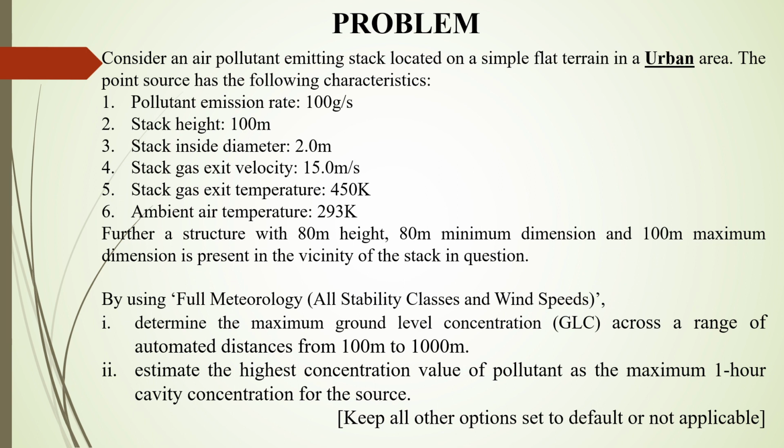The point source has the following characteristics. Pollutant emission rate is 100 gram per second. Stack height 100 meter. Stack inside diameter is 2 meter. Stack gas exit velocity is 15 meter per second. Stack gas exit temperature is 450 Kelvin. Ambient air temperature is 293 Kelvin.